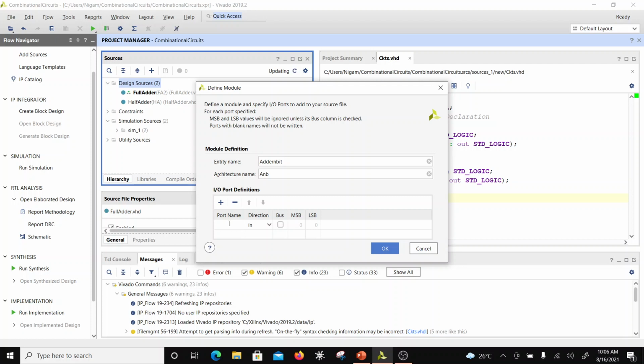So this is a vector, is a composite type, it is an array, right? It is the only inbuilt vector you will find in VHDL, or you have to create your own, right? So let's see what this is. So I can have A comma B, and this is going to be a bus or a bunch of wires. Let's say the default value is 8 bits, so 7 down to 0.